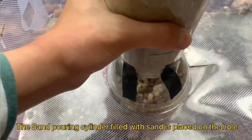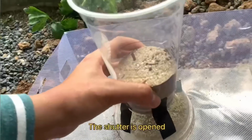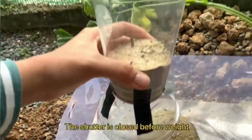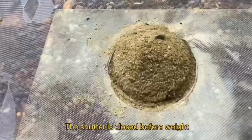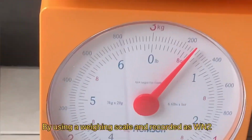The sand pouring cylinder filled with sand is placed on the hole. The shutter is opened to let the sand fill the excavated hole. The shutter is closed before it is weighed by using a weighing scale and recorded as WN2.